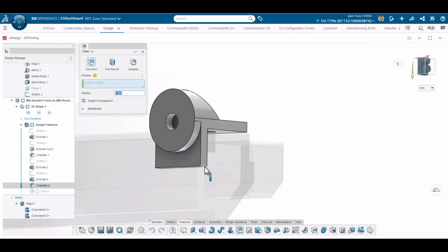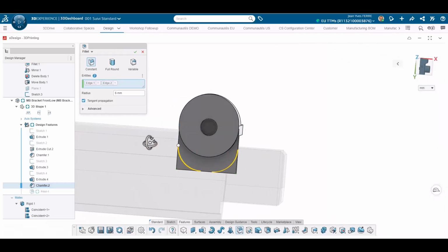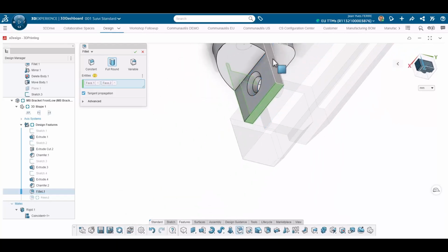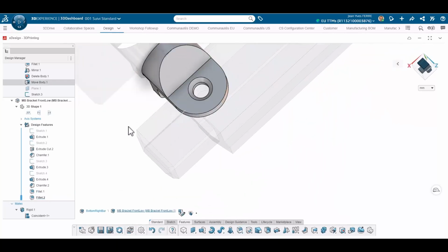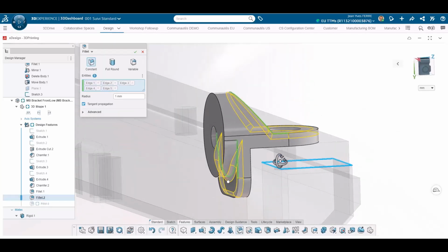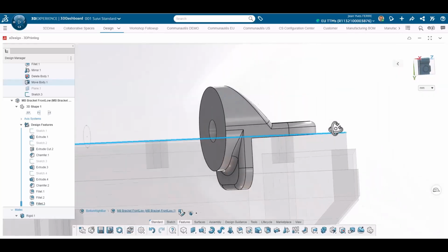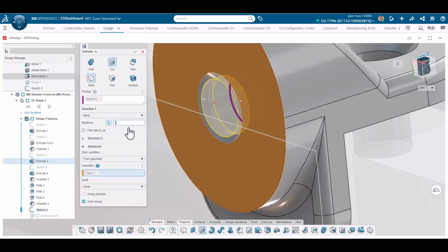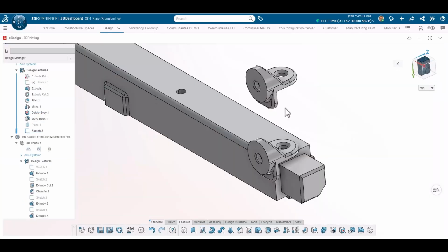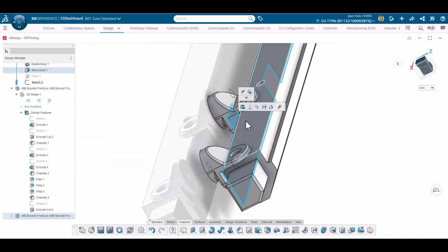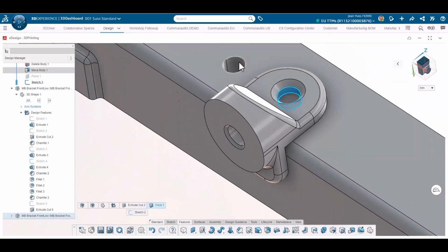Then I reinforce the part with a chamfer and I add some fillets, including this full round fillet to round the full tab in one operation. I add a general fillet and a last chamfer, and I make the mounting hole deeper to host the embedment nut properly. First mounting post is done, I reuse it on the next hole. A couple of simple mates and it's already in position and ready to use.